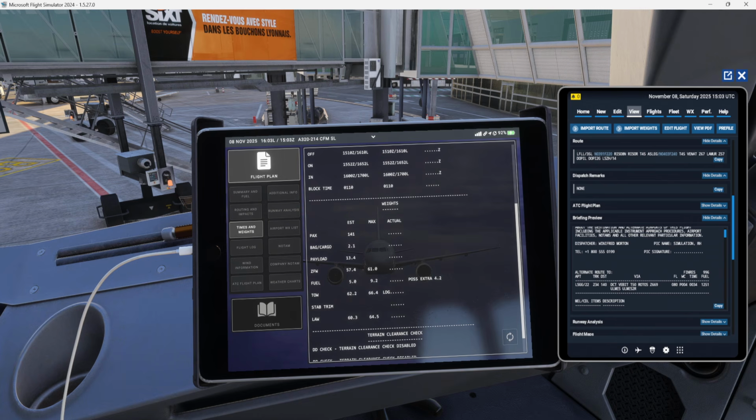Then to the operating mass you add the traffic load, you get the takeoff weight. In this case, we cannot calculate it because it's not important. The most important ones are zero fuel mass, takeoff mass, and landing mass. And takeoff mass plus run up and taxi fuel, we get the ramp mass. Okay, my friend.